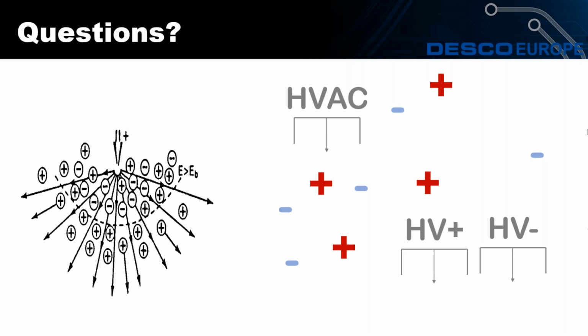But in terms of people, charges are generated on people all the time, every time they move, and they come into intimate contact with the susceptible device. So the idea of being able to generate a charge on yourself and then pick up a device, ionization is not going to deal with that anywhere near fast enough to provide adequate protection to the device.